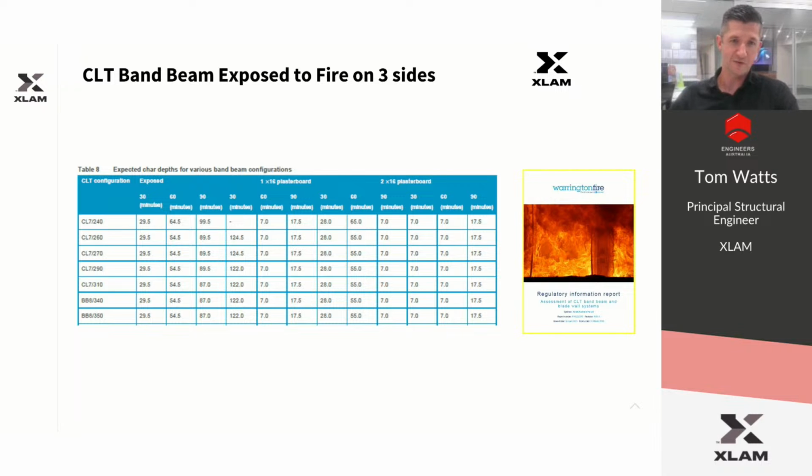So again, that's similar to the previous table where it shows for different periods of fire exposure, whether you want to expose the band beam, have one layer of encapsulation or two, how much char has occurred, and then you feed that into your residual section calculations.